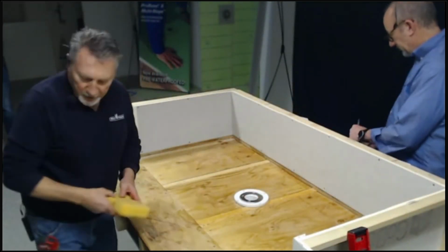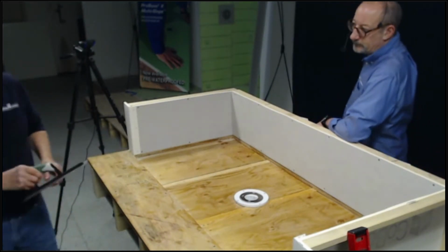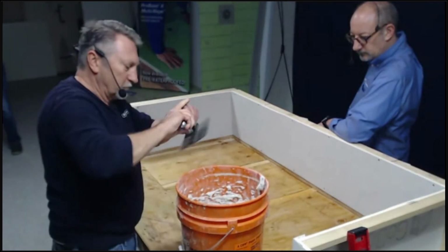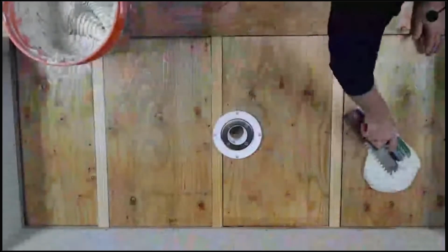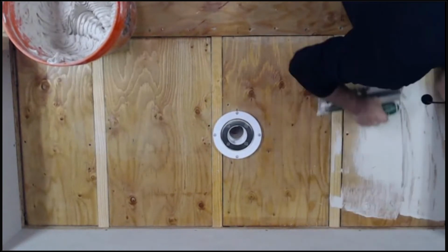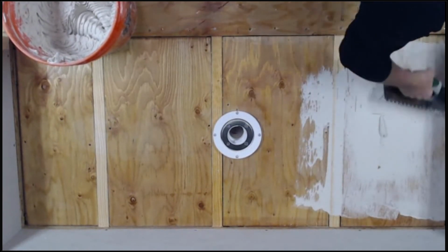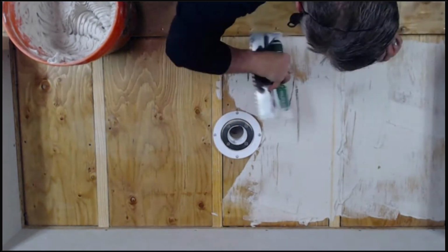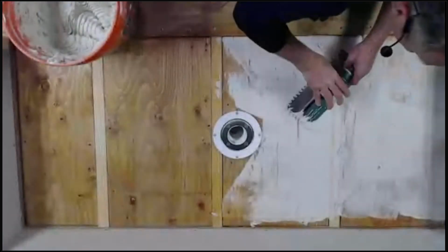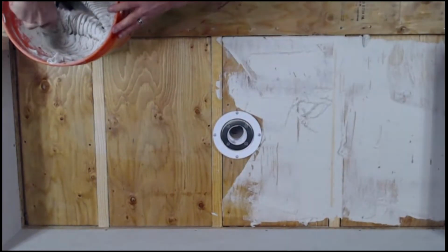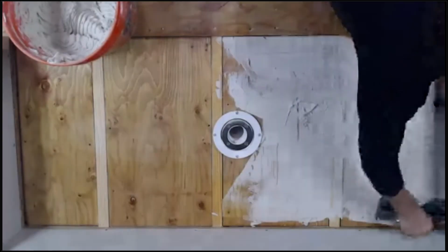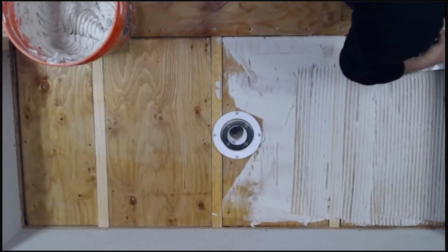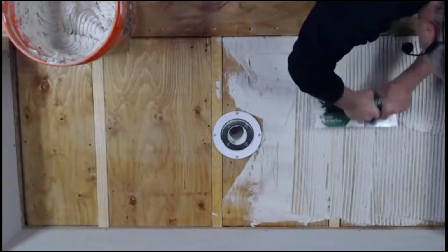Okay, I'm ready to apply my thin set. I'm going to be using a 1/4 inch notch trowel to apply it. Again, you would key it in just like you would any surface normally. Make sure that you get a nice bond to the substrate. The keying is important to make sure you get it into the grain. I will directional trowel it, just like you would with tile, so that when you put the base down, all the air is going to escape. Make sure you get good even coverage.